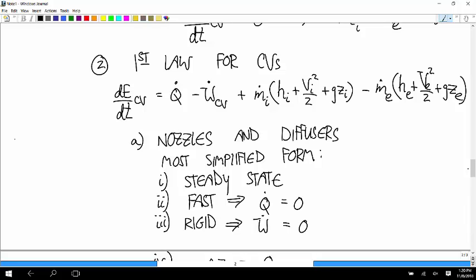And the enthalpy, if you're reading that out of a table, which you very often are, it's going to be given to you in kilojoules per kilogram. Okay, and so those units don't match. So if you're combining kinetic energy or potential energy calculations with enthalpy from a table, you need to re-express that enthalpy in joules. So whatever number you read out of the table, multiply that by 1,000 to put it in joules. Otherwise you have a unit mismatch and everything's haywire.